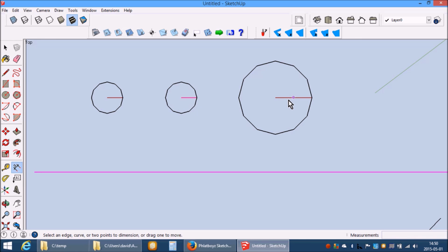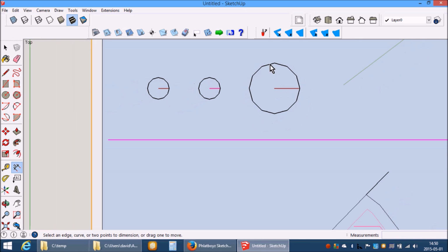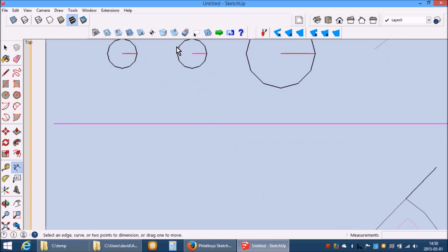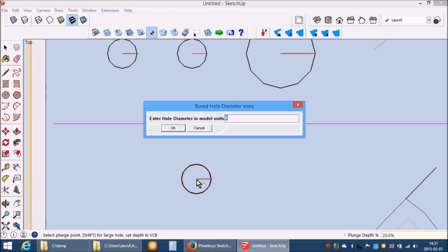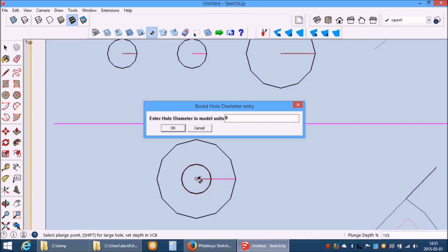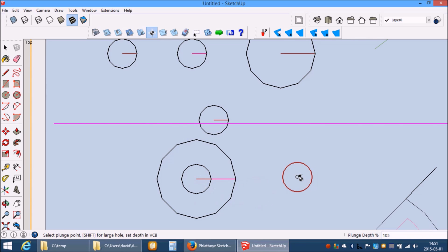And the color is dark brown, which indicates a full depth hole. If I want to do a partial depth large hole, as for doing a recess for a cap head screw, I can drill a hole all the way through, and then I can select a depth and a size. That will create a recess with a hole through the center for a cap head screw or similar.